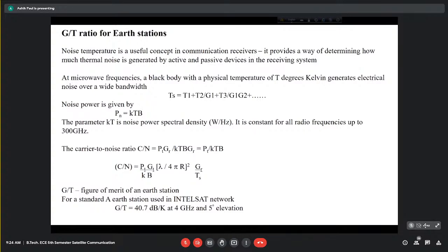If it was cos omega t, it becomes cos square omega t, which you can resolve into a cos of 2 omega t term. So a higher frequency is generated when the signal passes through that kind of nonlinear device in the receiver.